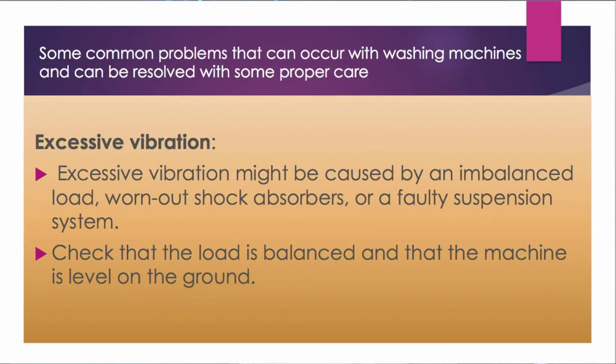Another important problem that is seen many times is excessive vibration in the machine. Excessive vibration might be caused by an imbalanced load, worn out shock absorbers, or a faulty suspension system. Check that the load is balanced and that the machine is level on the ground. If this doesn't address the problem, in that case you have to contact your authorized service center for repair.